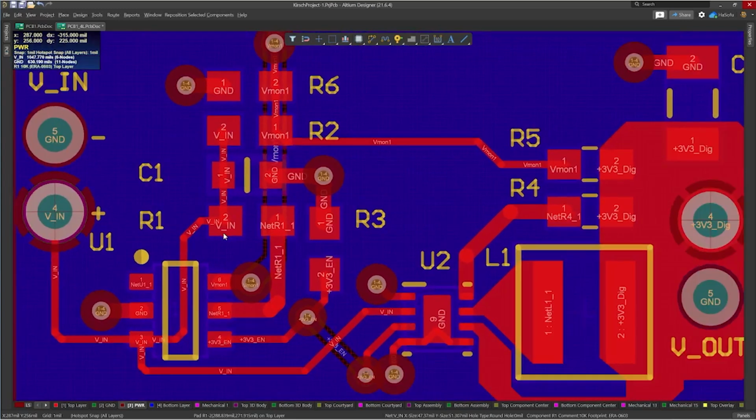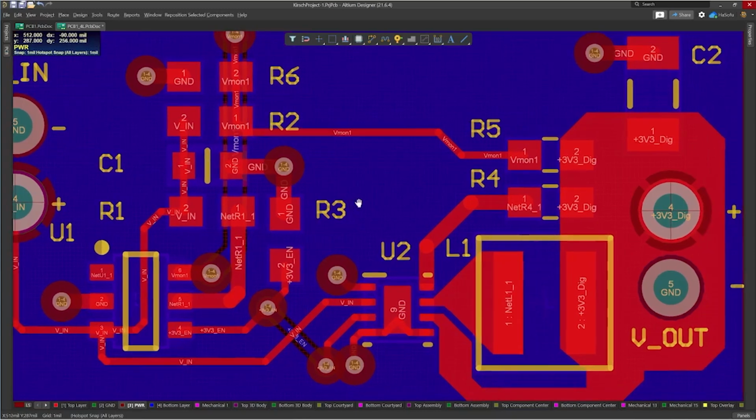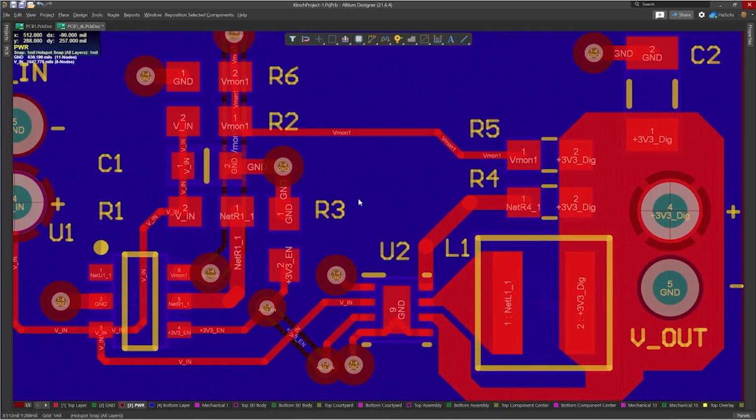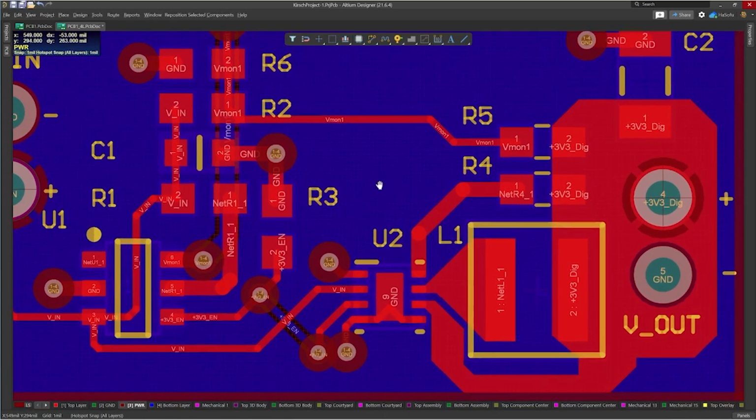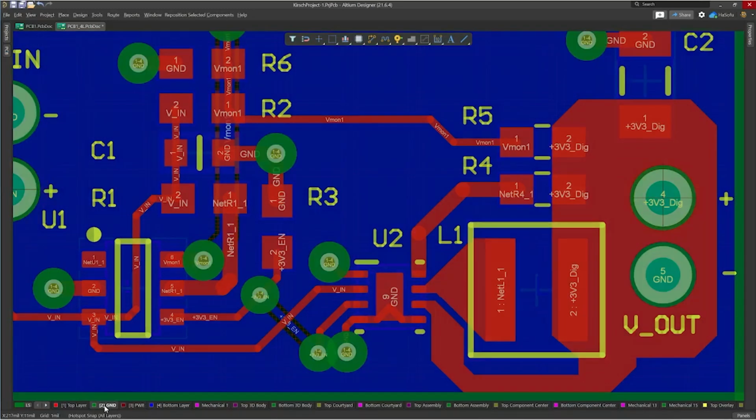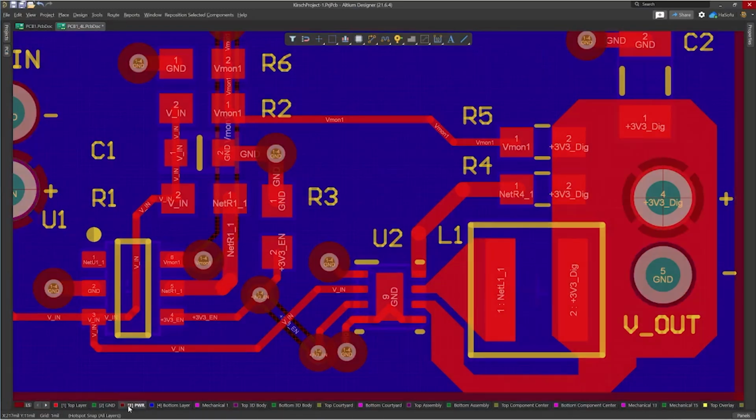If you can get lower impedance voltage supply rails or voltage nets, then you want to do that. Also, having a power plane directly adjacent to some ground plane helps with capacitive coupling and providing free capacitance that would help source currents.